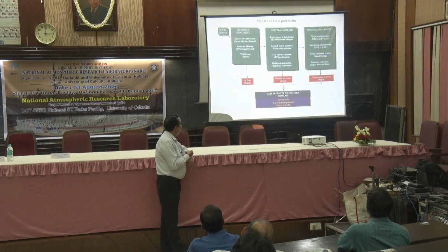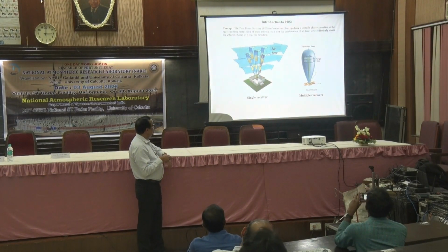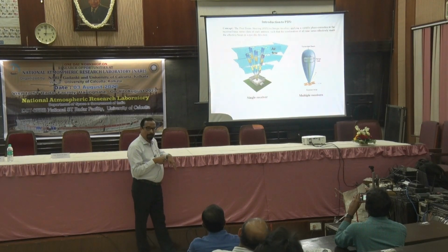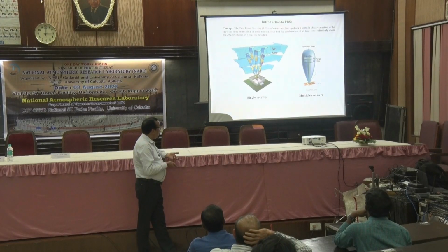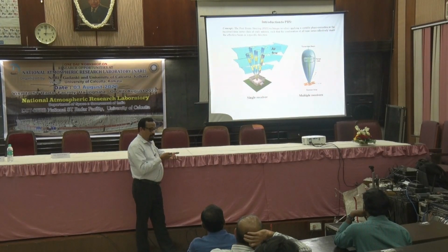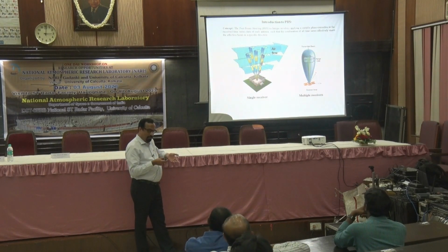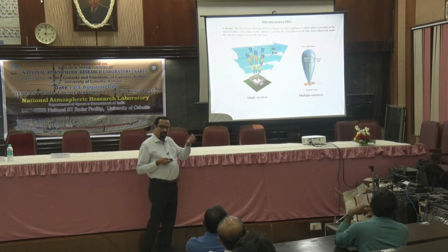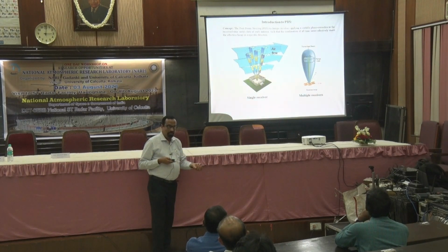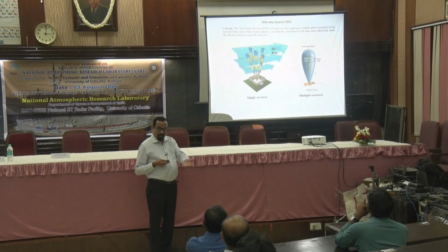I think one chart may be there. Yeah, this will tell you the process. I have the transmit beam. This is what I transmitted. I received with the same array. All components are independently digitized and taken back. Instead of doing it in the vertical, post facto I apply my phase shifting onto each line where the signal is received. So this is an opportunity that again exists in this radar now.